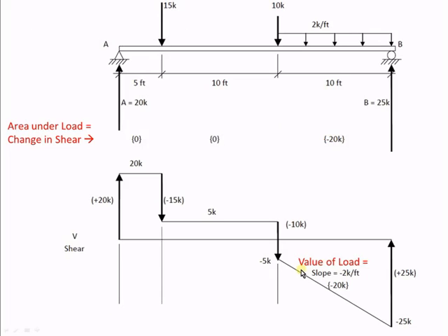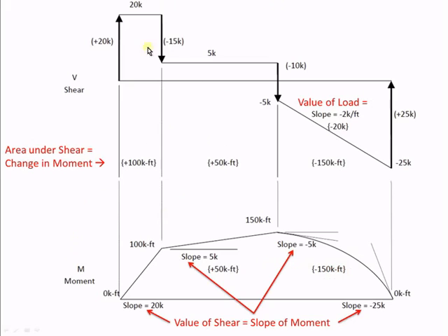Okay, so in your handout you have another example that you could use to work through if you want. And so I've drawn everything here to scale. Actually, in Word I drew this entire beam to scale, so it's a little bit more complicated. See if you can understand how to just graphically go from here to the shear diagram, and again from the shear diagram to the moment diagram.